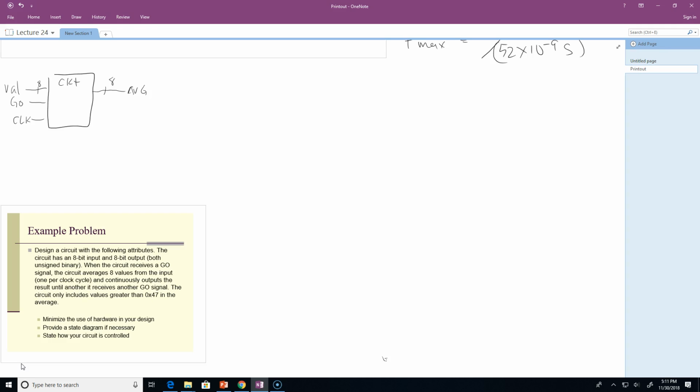So in the end, 8 is 2 to the 3rd times 2 to the 8th equals 2 to the 11th. I got that wrong at first. This 11 is going to be the width of my output, and numbers with 11 bits are never going to be maxed out by the 8-bit inputs.